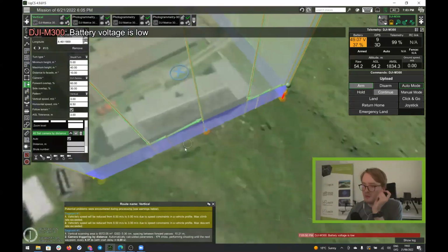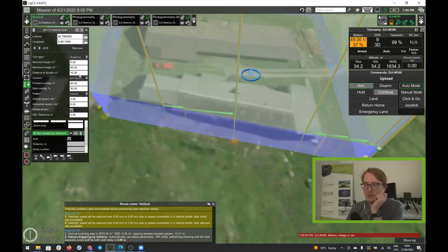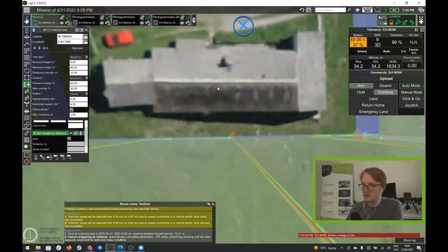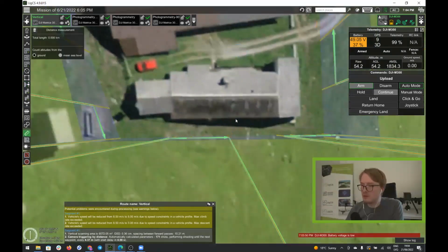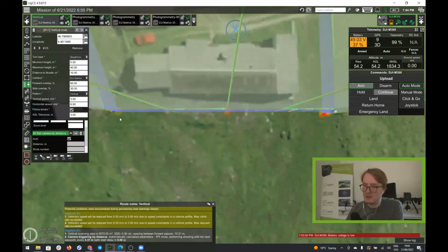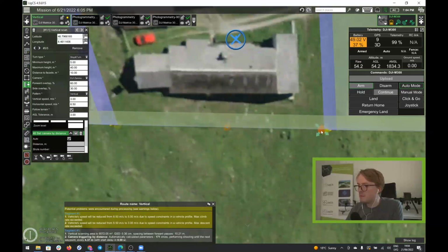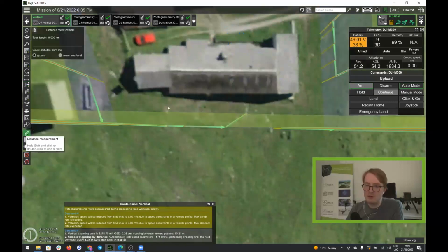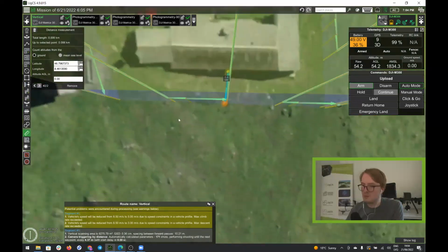And so, yeah, we have this camera selected. And then one of the main parameters here is actually the distance to the facade. In this case, the distance is set as 10 meters, and we can actually measure this in UgCS. So let's just zoom out a bit. Here we have the distance measurement tool. We can select it, and for example, here you can see this is the edge of the building, and then we can measure the distance until here. In this case, you can see that this distance is 3 meters. So this just means we might need to put this just a bit further. So maybe somehow like so, and then let's again do the distance measurement to make sure this is more or less how it's supposed to be, and we can probably move this even further.